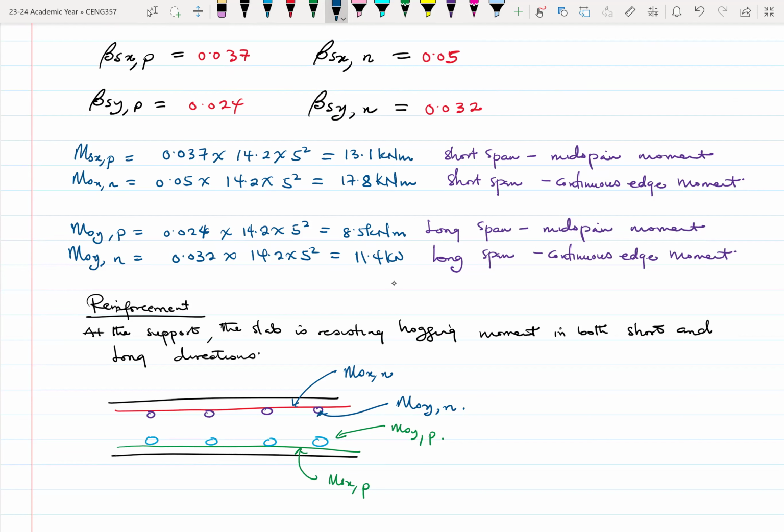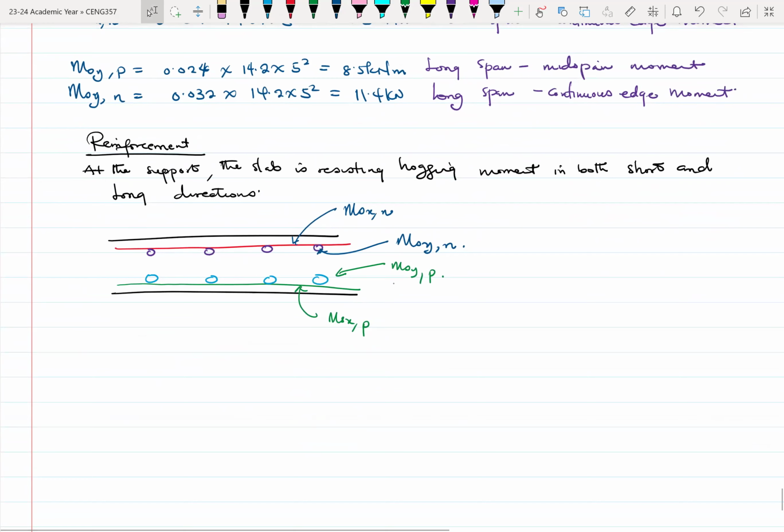So what's going to happen is that you have to note that the effective depth values, the D values, will vary. This is like how we had doubly reinforced beams, something very similar, right? So this one becomes like a doubly reinforced slab in a way. All right, so take note, the effective depth will vary.